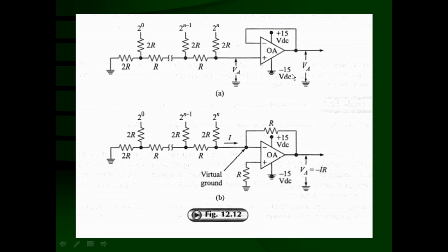So output voltage is equal to input voltage. It is in the same phase, and this non-inverting terminal is connected to the output. That means it will provide a feedback resistance of 0, and hence it is a voltage to voltage amplifier with unity gain and non-inverting amplifier.